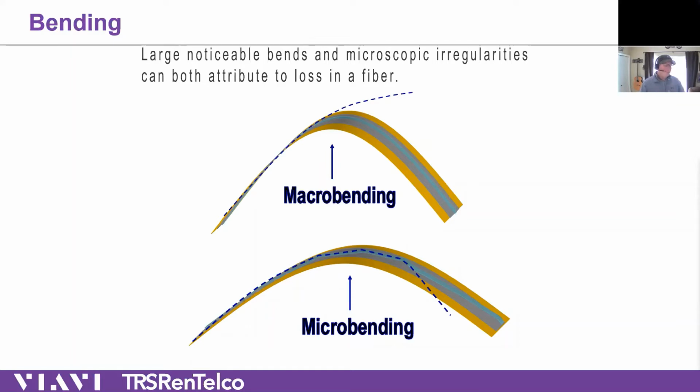One, connectors and splices act differently at different frequencies, and the network is evolving from 1310 to 1550, which we'll talk about with 2 slides here of why. And when you shoot those wavelengths, the macro bending can be calculated by the OTDR, and we can give you a pretty good accuracy saying that's not a splice, that's not a break, but you have a bend in your cable, and where is it?